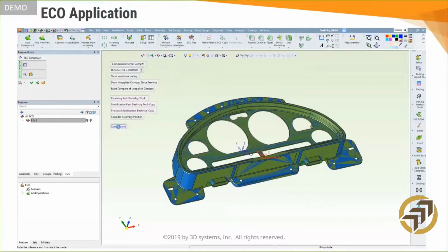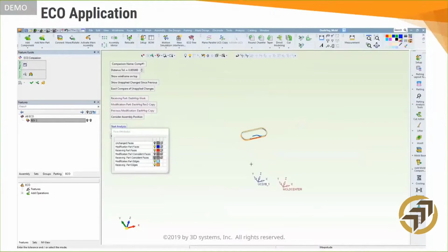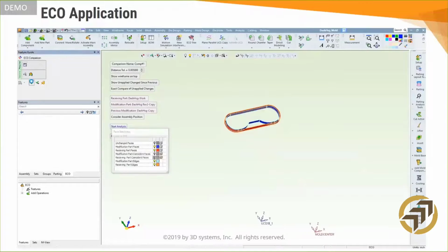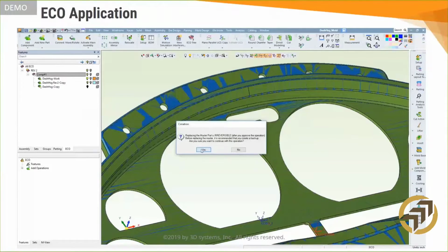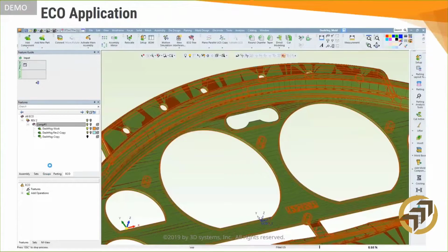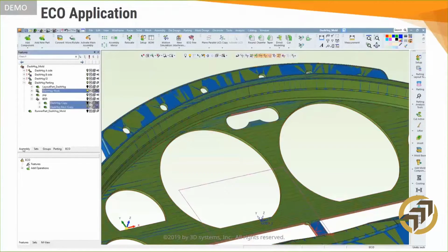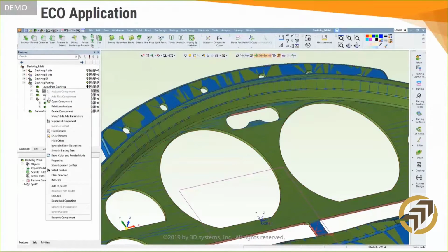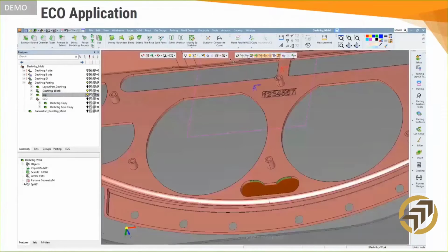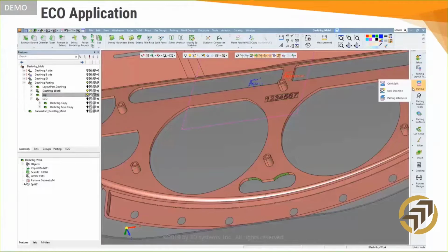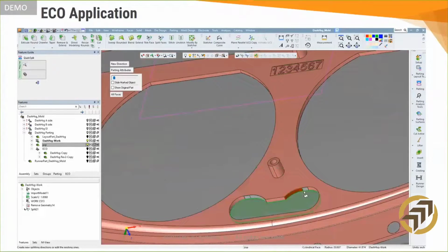An extra bonus at this step is the ability to add a third part to the comparison, the one you added any draft or molding features to. This filters the comparison result even further, keeping your part preparation work safe from replacement. Once identified, the part changes need to be applied. An update passes them into the splitting model, where the system actually reapplies all of the parting and shutoff work you originally did on top of the new geometry. This amazing recalculation of existing design work might only leave a few areas for the user to sort and check, and reduces the time spent on ECOs to an absolute minimum.